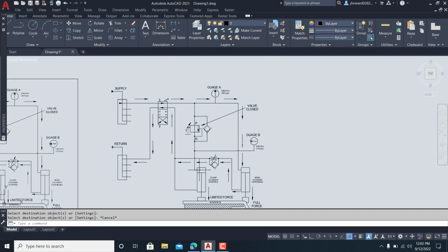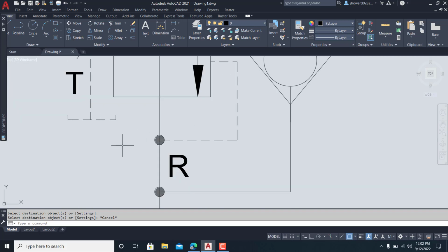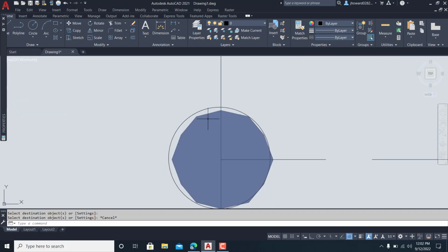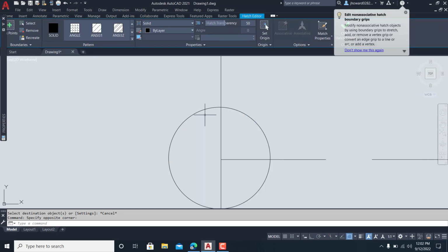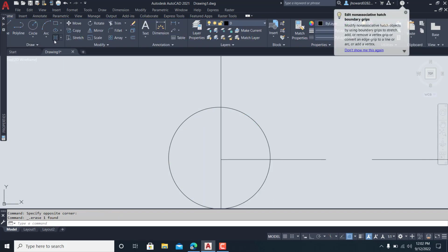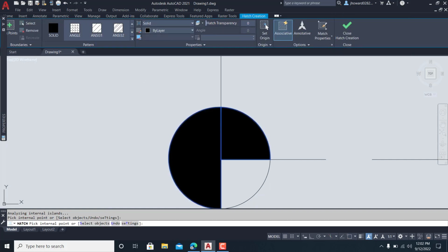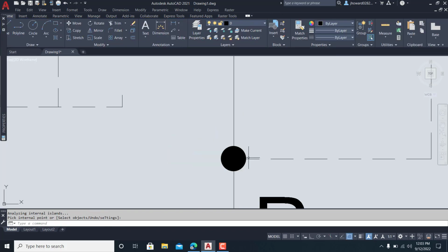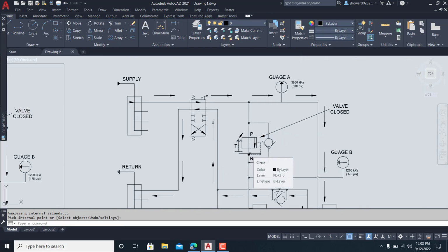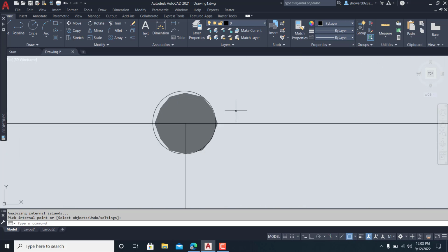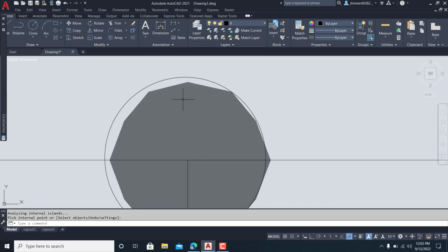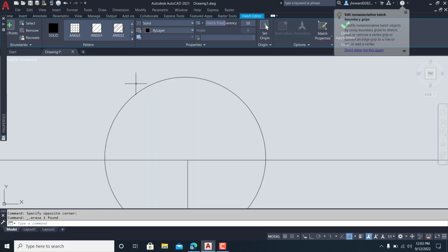Do you notice that when I zoom in here, that this hatch isn't filling that up? What you'll have to do is go in there and delete that out and come in here and put you a new hatch in. And fix those points. There's just a few of them, but that's one of the faults that it does have. It doesn't pick up hatches exactly right. See how it's missing the point? So just delete those out very simply and easily.